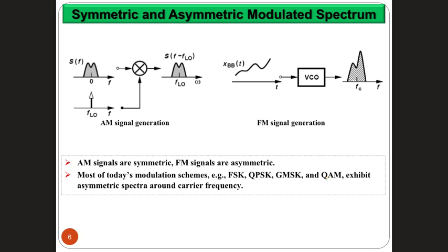Because if you use phase, then the signal is moving between real and imaginary, so many components of the signal will have an imaginary part. And if you use FSK, it's again a kind of frequency modulation, and we saw that frequency modulation by nature is complex. And if you use QAM modulation, again by nature, you are using imaginary and real. So you always have this situation in almost all digital communication. This is why you probably mentioned digital versus analog.